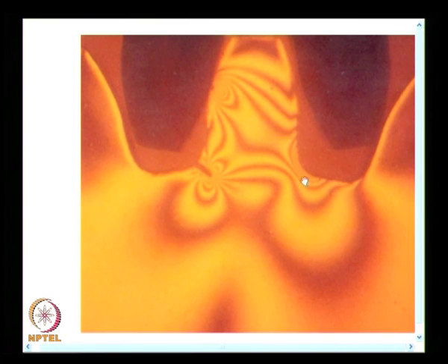And suppose, for example, I need to measure strain on this fillet, you could see there are many fringes densely packed in this corner. So, that indicates obviously you have a stress concentration zone, and if I have to measure strain in those locations, I can't use the general purpose strain gauge of length 3 millimeter. I need to use a strain gauge smaller than that.